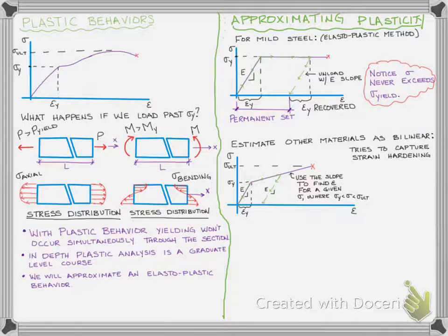So you can actually use the slope of the secondary curve with the stress that you're at a certain point to just then pick the E value that you're at when you start to unload. And so then you can determine your elastic recovery, at which point you can also then determine your permanent set. So that just becomes some geometry and trig, and that's all that's happening there.